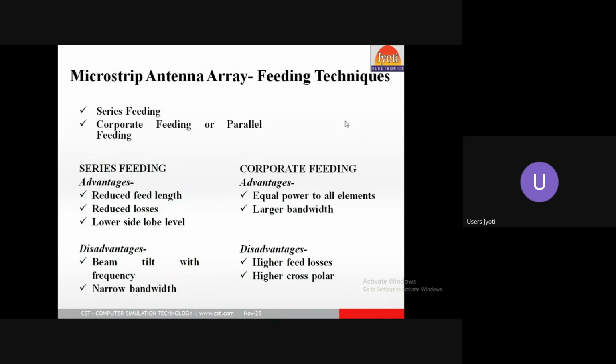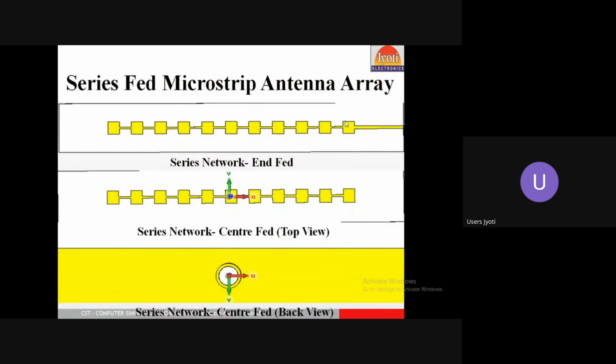Also, the feeding network is important. As we previously said, there are different types of feeding networks, but here we take a waveguide port feeding network in different ways. There are discrete ports and waveguide ports. So the feeding network is also important for beam steering and beam capabilities. If we see it in a MIMO antenna, the series feeding and the parallel feeding of the antenna are also important.